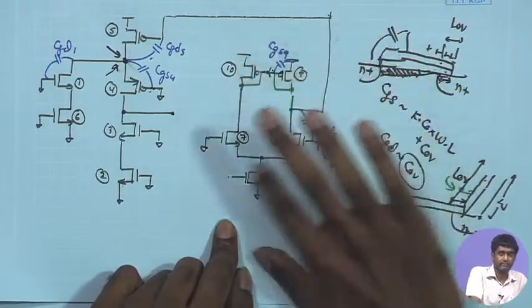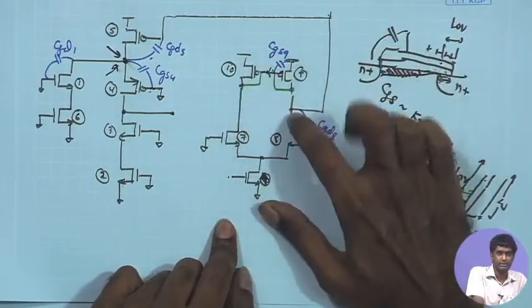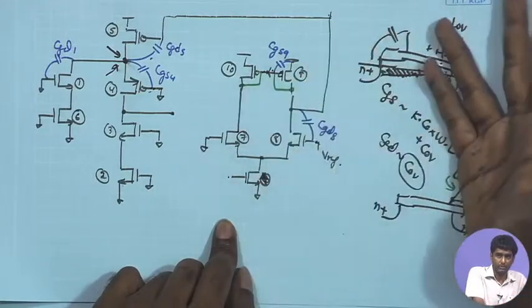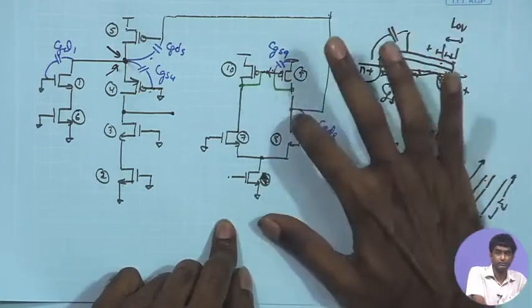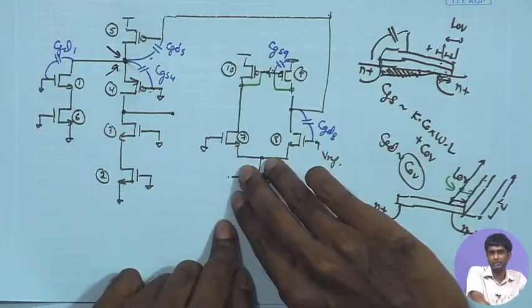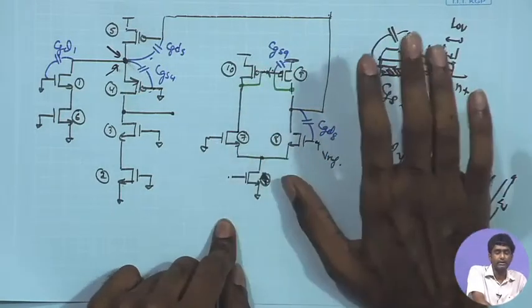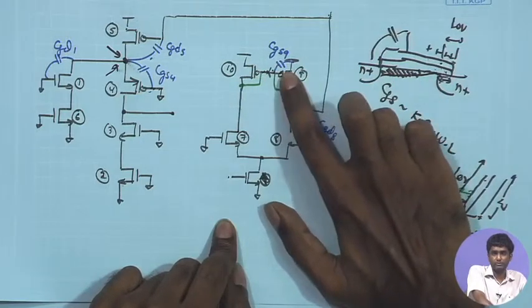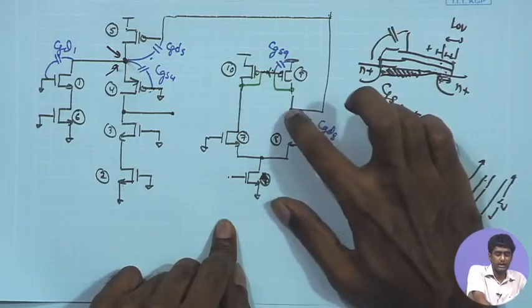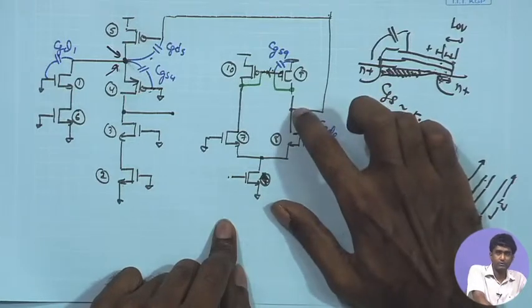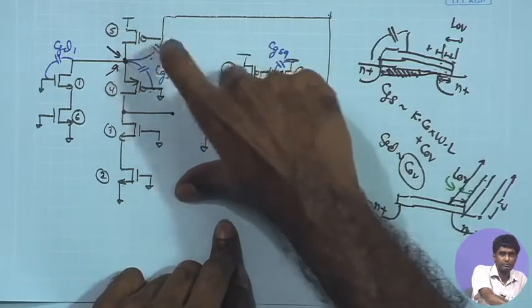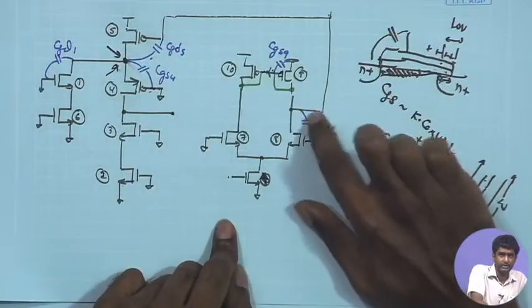So, if you are trying to save the bias current in this stage by reducing it aggressively, the overall small signal resistance over here will become maybe close to RO, because if you are in subthreshold regime, transistors are having very small current, microampere or close to that, the GM can be pretty poor, especially if on top of that, you choose a poor W by L for this, and in that case the overall small signal resistance over here can increase, and then you also have this Miller multiplication for CGD5 coming. Those things can complicate the stability issue a little bit.